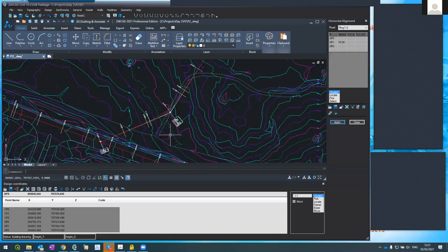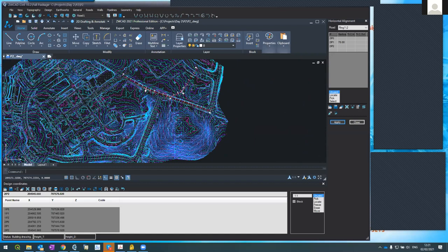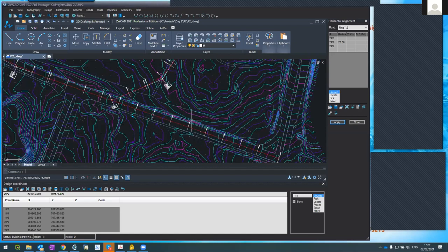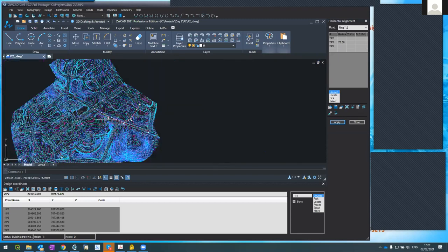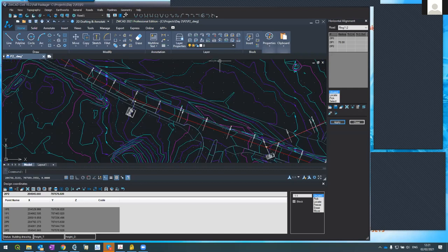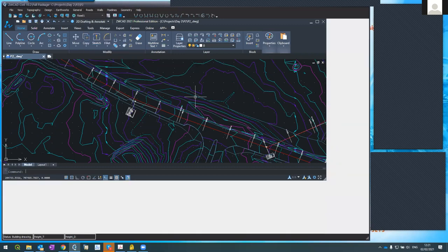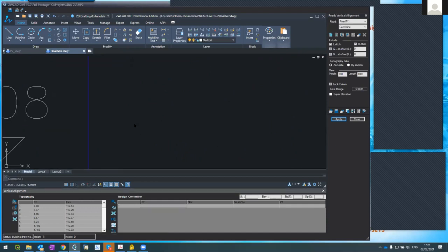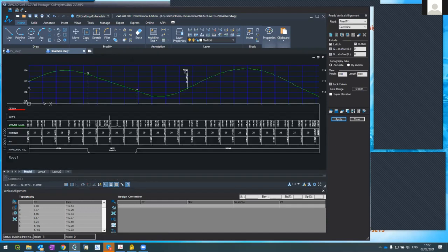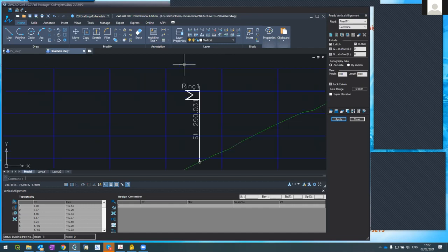So I created a second road, this one, which is a rehabilitation of the existing road, or I would do it as an extension, and this one, which is a new link. And let me go to the design. Flip to road number 1, go to roads, vertical alignment. Apply. Good. This is the profile. You can see that this is the existing road. This is the flag. So what I'll do, I'll design more or less now like the existing road.